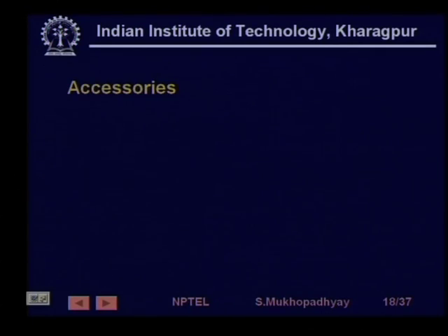So, obviously compressors, apart from that mechanism, require other accessories, like for example lubrication. Lubrication is very important in pneumatic systems, firstly because they are not self lubricating, just like hydraulics. So, you have to have special lubrication mechanisms here, and second also because the tendency of air to leak is actually much more than the tendency of oil, because air has very low viscosity and oil has high viscosity.